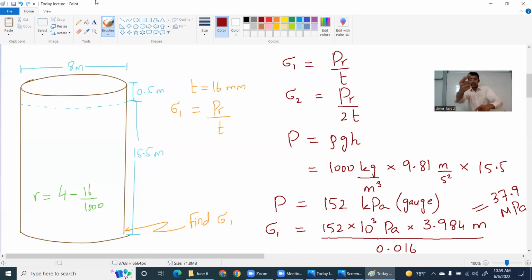So for example, I will put a line over here like this. I will say that this container is welded, and the weld angle is 15 degrees. I will say if the container is welded, tell me the kind of stresses that this weld is subjected to. So what will you do? Sigma 1 is with you, sigma 2 is with you. You have to go through stress transformation equations or Mohr circle.